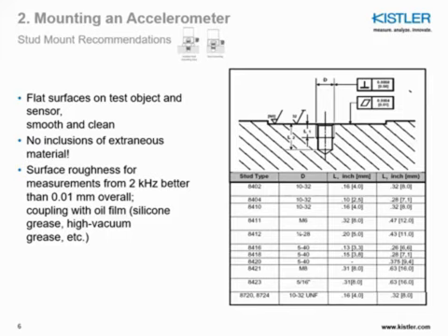Before mounting the sensor, if you are doing a mounting where you are required to have an isolated stud, you always need to check that stud for damage. Heavily anodized aluminum studs may be scratched and no longer insulate adequately. On the other hand, if you use studs with ceramic inserts, depending on the design, you may have inadequate transverse rigidity, and the upper temperature limit can be very critical in such cases.